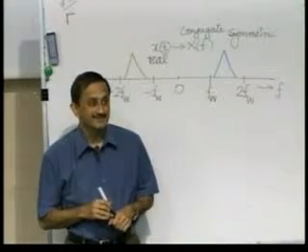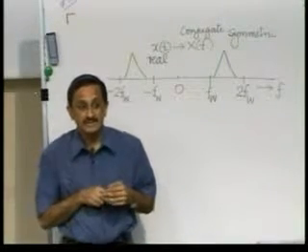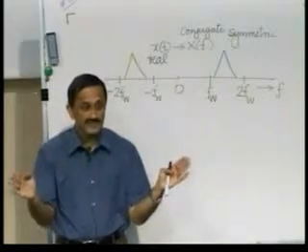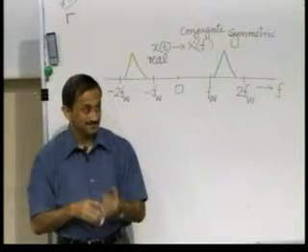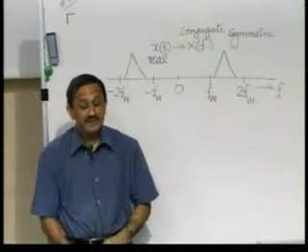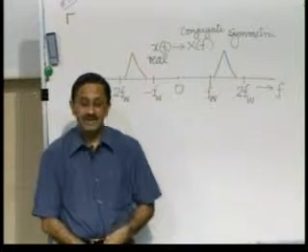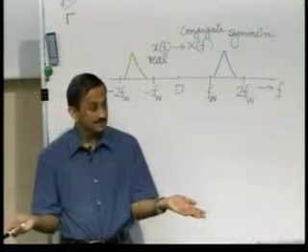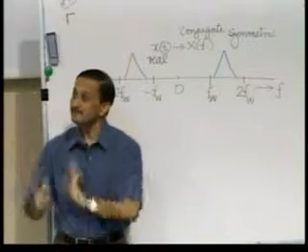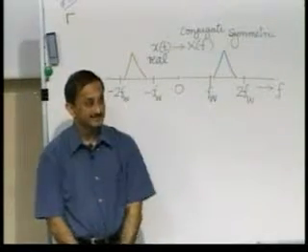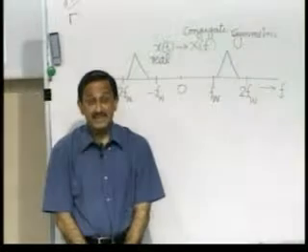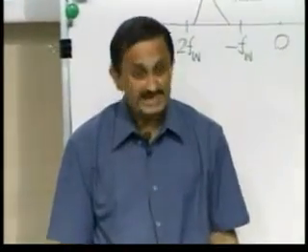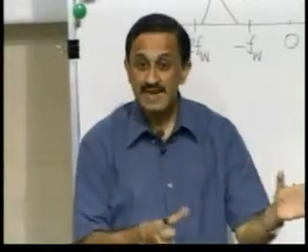Now, at this point, a little aside. If you look carefully, the reason why we get the requirement of 2 times Fm is because the signal is real, and actually on the frequency axis it occupies a range of 2 Fm, from minus Fm to plus Fm, right. Now, we might be tempted into asking the following question. Suppose I have a complex signal, whatever it might mean, then I don't have conjugate symmetry. So, it is quite possible that I might have a spectrum of 2 Fm on the negative frequency side. Can I get away by sampling at Fm? Well, indeed I can, because the original spectrum would get translated by every multiple of Fm, and these translates would be non-overlapping.